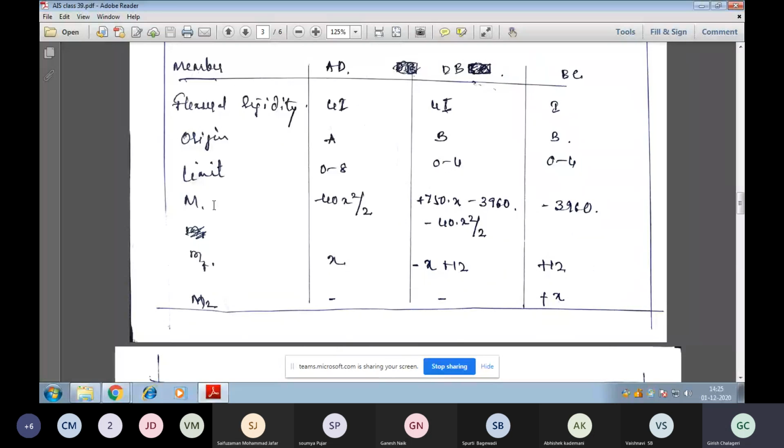Next comes the M, M1, M2. Capital M is the moment due to the external loads applied over the members. M1 is the unit load applied in the upward direction, for which we get the deflection in the members. That will give M1 values. M2 is the horizontal force what we applied at the coordinate second point and finding the deflection at the required points.